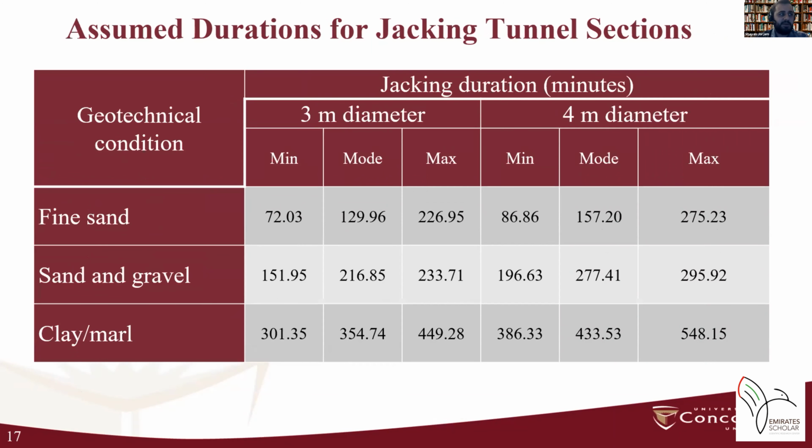Because of the difference between the dimensions of the assumed tunnel and those of the tunnels in the reviewed projects, the jacking duration was modified according to the diameter and length of the sections. As an example, we can see in this table that in a 3 meter diameter tunnel in fine sand, the jacking duration is about 72 minutes.